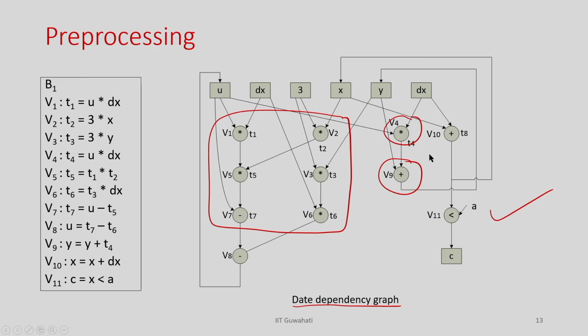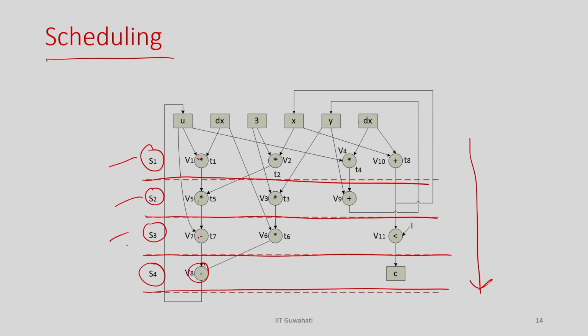So, overall I understand that this particular control and data flow is important, and from there I can understand the order of the clocks and what total clock count is needed after the scheduling. Okay. So, that is understood, that this is the operation to be executed in time step 1 and so on. Now, the question is how this operation is going to execute in hardware, because there is no hardware with me. I just decide that for the for loop or while loop I need 43 clock cycles, but I never decide where this operation is going to execute, because there is no data path to me.